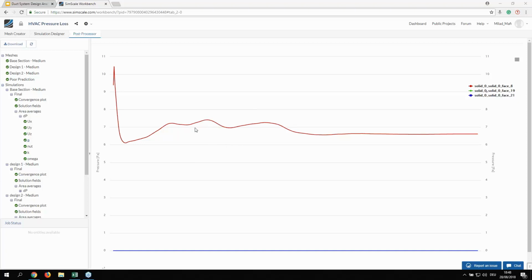Then there is a question by Justin, and he wants to know if the ASHRAE fittings database values have been simulated, and if yes, how to compare the simulated results to the published data. That's a very good point, and actually the ASHRAE fitting database uses a semi-analytical approach of using, at the end of the day, loss factors for different kinds of data sets.